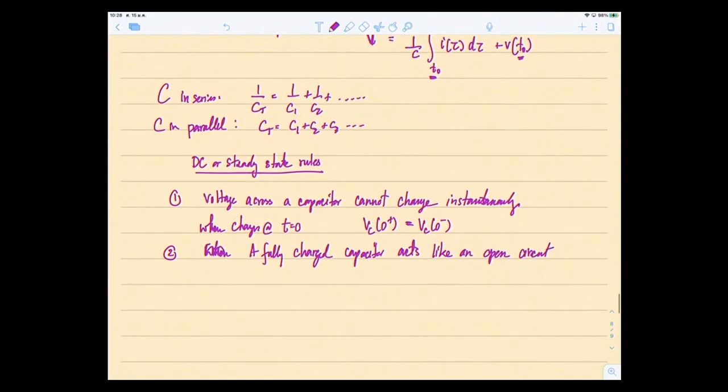If you have a capacitor and there's some V, let's say V equal to VC, and it's a constant value, then due to the formula I equal to C dV/dt, if your V is a constant value, then it becomes 0.